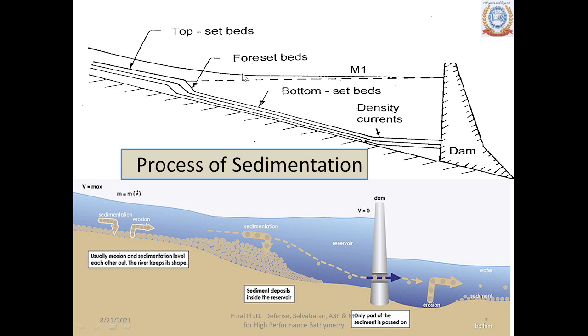Now, the satellite based bathymetry survey that the Central Water Commission is so far doing is based on imagery collected at the surface. The surface imagery will show the reduction in the catchment, the reduction in the water storage boundary space. However, it does not see what is below your MDDL level, the storage which is being eaten away. To map or measure this, you have no method other than putting a boat on top of the reservoir and measuring what depth is reduced. So that is the way.